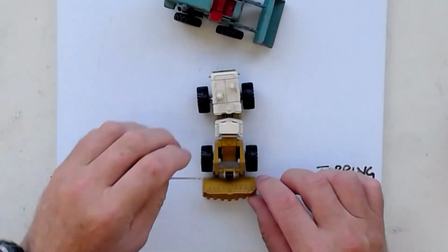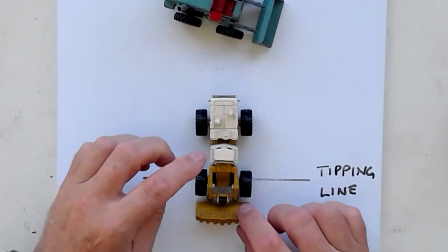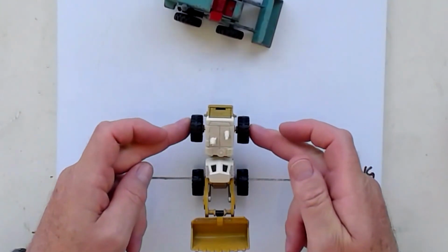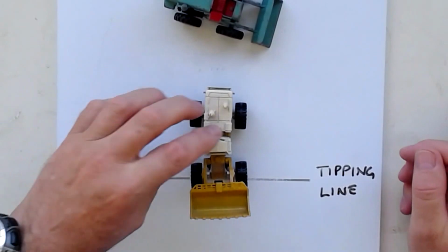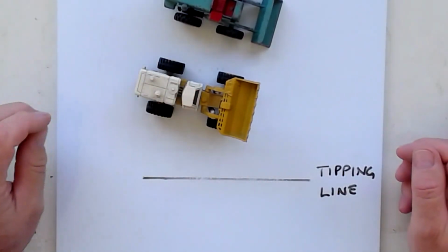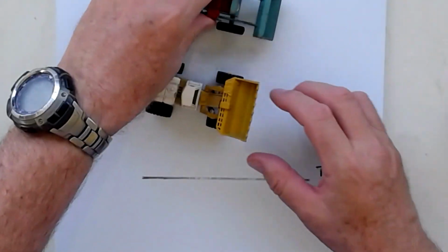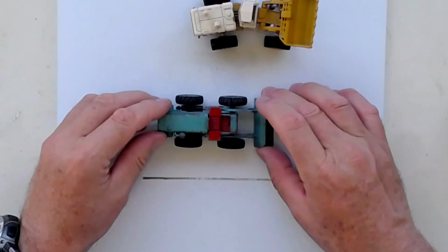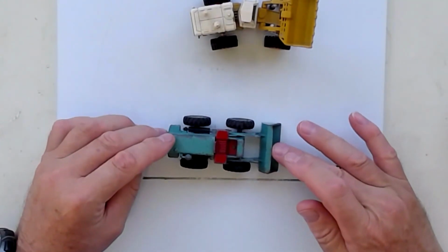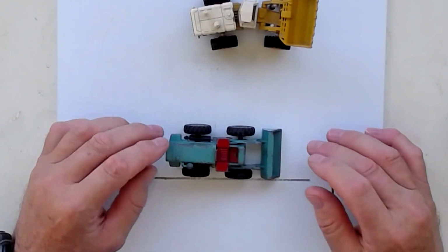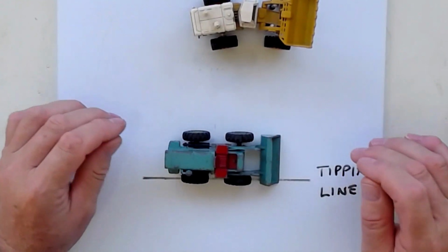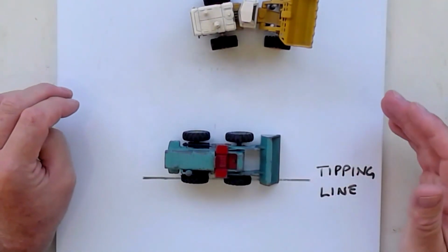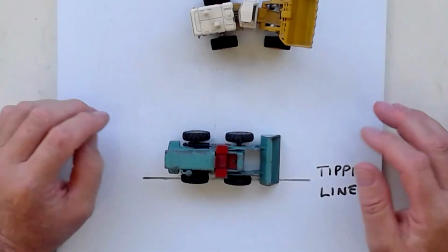It's exactly the same thing here for an articulated vehicle. Carry too much load and you're going to tip over. That's a fairly straightforward thing. You've seen the Ventrac tractor as I've used for examples previously. I've tipped forward 3 or 4 times and nearly been disemboweled on the steering wheel. And in all those cases, it's happened when I've changed grade. So I've learnt to keep the bucket very low to the ground. But a rollover is a different situation.